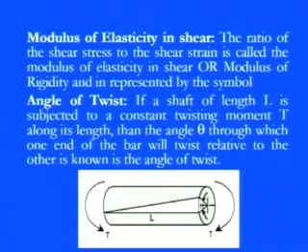So now what we are doing here is simply saying that we have a stress and a strain. Since both stress and strain are shearing components, and we are assuming that under the application of the twisting moment or torque the deformation is elastic, we can simply apply Hooke's law, for which we always define Young's modulus of elasticity. But since here the shearing action is there, Young's modulus will not apply, because Young's modulus is only applicable wherever normal stress components are there. So here we apply the shear modulus of rigidity, because shearing action is there.